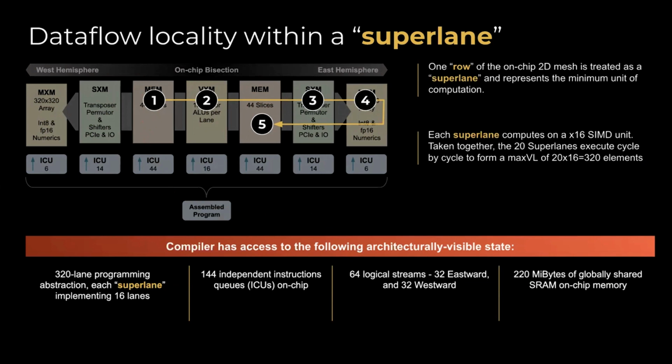And stream registers are similar to the normal general purpose registers that you're used to. For example, if you're used to a traditional conventional CPU, where you do a load into a general purpose register, say a load into register 3, you can come back a week from now and the data that you loaded will still be in register 3. That's because that data is static. This is different in that when you do a vector load into a stream register, it literally starts flowing east or west onto the chip.